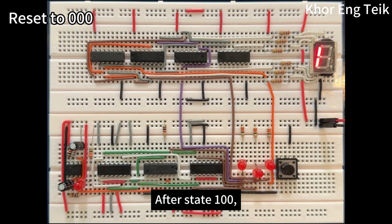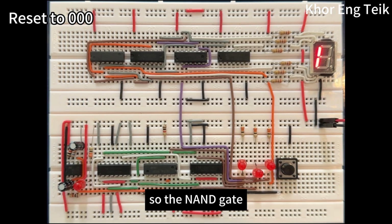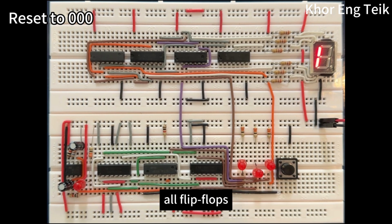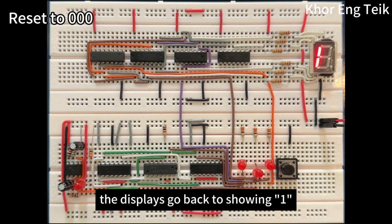After state 1, 0, 0, the next clock pulse would bring us to 1, 0, 1. However, we do not want states 1, 0, 1, 1, 1, 0 and 1, 1, 1 to appear. So the NAND gate detects when the state reaches 1, 0, 1 and immediately sends a clear signal to all flip-flops, resetting everything back to 0, 0, 0. The display goes back to showing 1 and the cycle repeats automatically.